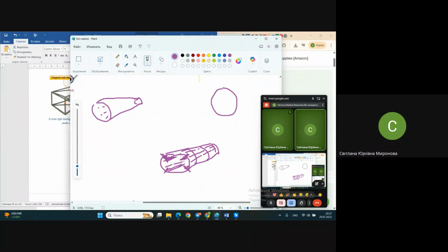And semi-monocoque consists of skin supported with dozens of these stringers and supported with transversal elements, frames. It's for the fuselage. Once again, I remind you, it comes to three types of beam-like fuselage. And the most popular by now are these semi-monocoque structures.